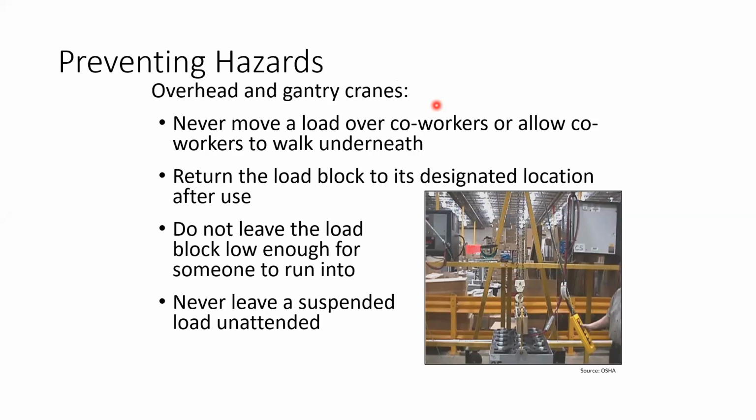Number two, return the load block to its designated location after use. Number three, don't leave the load block low enough for someone to run into. Number four, never leave a suspended load unattended.